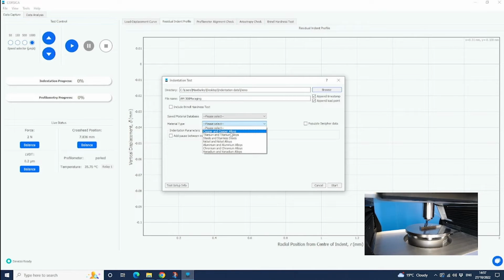So sensitivities work for us in so much as steels will typically range from 190 to 210 gigapascals, and that range doesn't phase us at all. Aluminium, however, down at 70 gigapascals, if we were to choose that and test the steel, that would introduce some errors. So this is the only step that is required of us. We can select steel, so if you remember from the demo I was testing this Mar-aging steel.